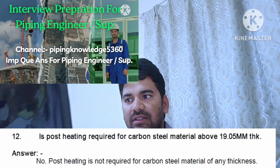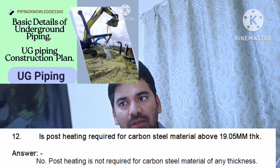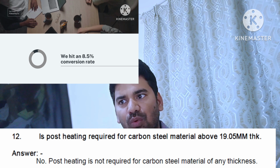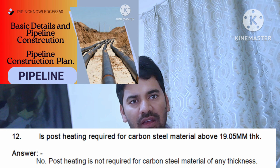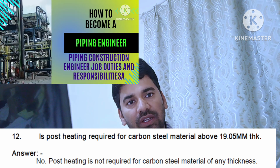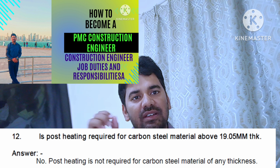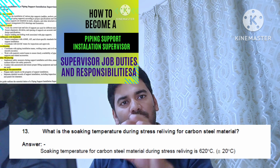Okay, the next question is whether post heating is required. Post heating is not required for carbon steel pipe of any thickness. If your CS pipe thickness is 19.5 mm or more, then you require preheating, and the preheating temperature is 80 degrees Celsius. But there is no post heating in carbon steel pipe.